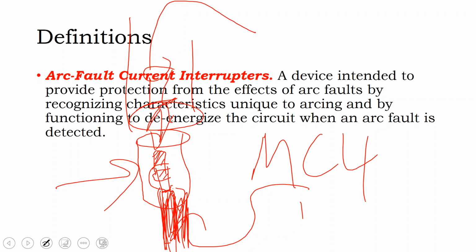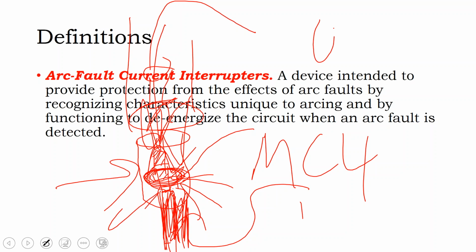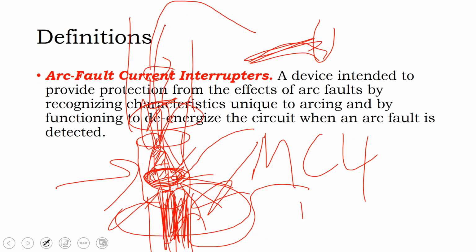When you get into the solar brass tacks, even though MC4 is a standard, there are different MC4 connectors out there, and while they're all compatible with each other, the difference is this little crimped metal piece that forms the actual thing that's getting plugged into each other. Does it go completely around? Is it a circle that is crimped on all ends, or is it a U channel that might slip? In addition, there's a little nut at the bottom of this connector that's used to tighten it up. It's a little messy up on screen, I know that.